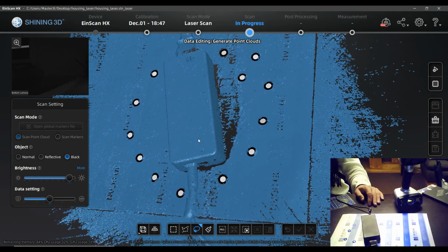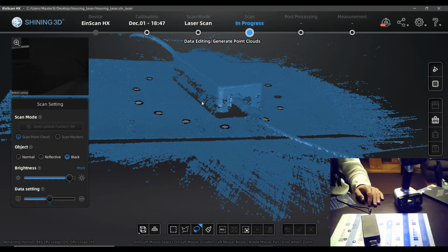If you have to turn the scanner very much to scan some perpendicular surfaces, there can be a need for additional markers that are visible in the moment when you are turning the scanner. It can as well be a problem if there is no space for the cameras to capture, but you are able to do this after a few scans. You will have a feeling after some first examples where to apply and where not, and so on. That's just a question of time. You now have all the basics you need to understand.